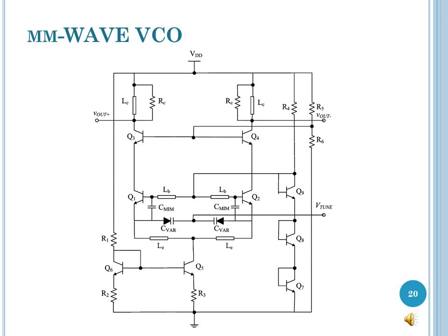The inductors at the collector of Q3 and Q4 form the output network designed to resonate at 60 GHz. Inductors placed in the emitter branch of the circuit implement the LC filtering technique commonly used to reduce the phase noise contribution of the current source. It also enables the use of a single current source instead of two. Other transistors and resistors constitute the bias network of the circuit, which supplies the oscillator current and also provides appropriate bias voltages at the required nodes.